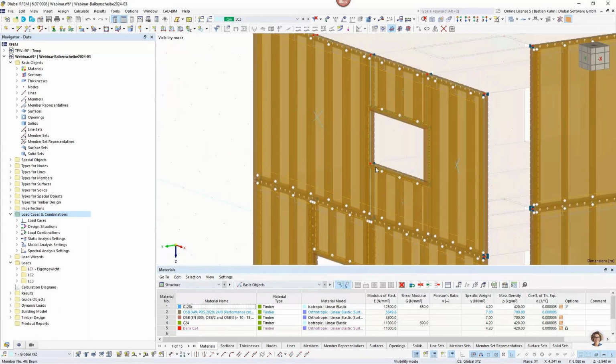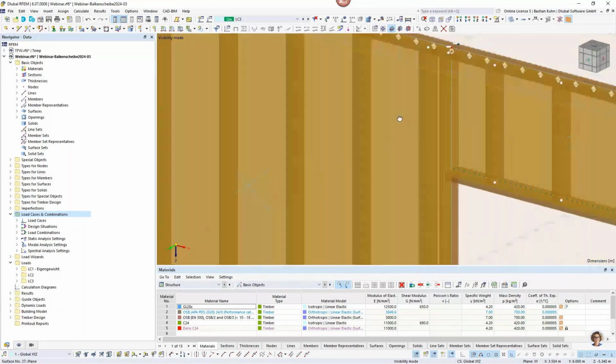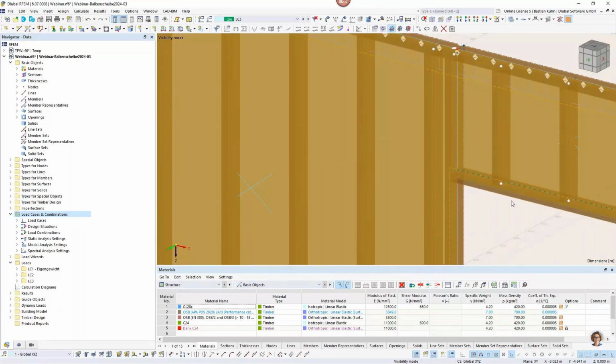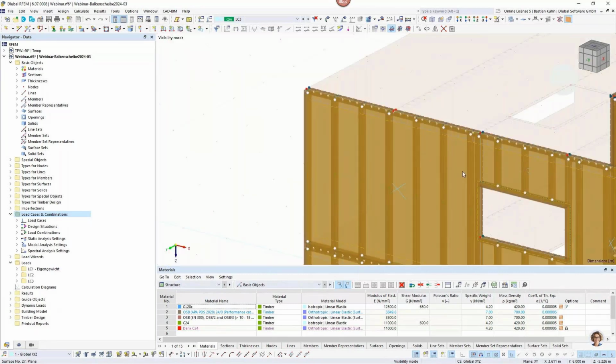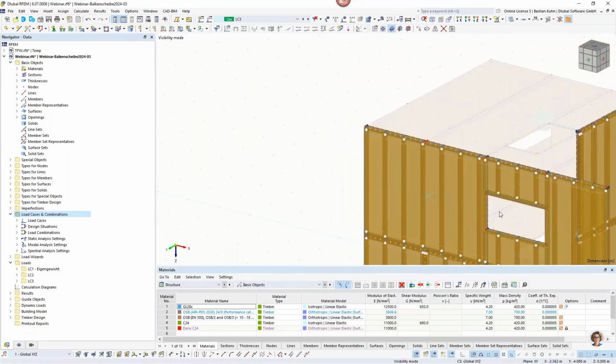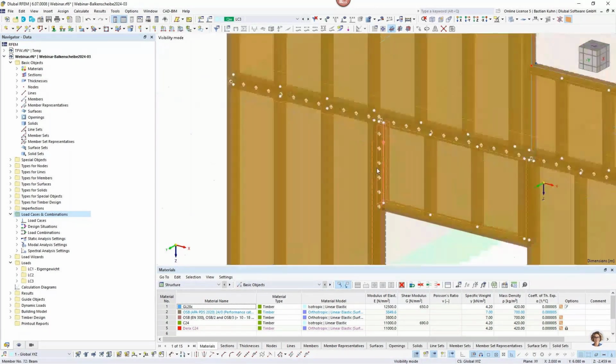Then what we do here in Europe is that we are using the top beam, or how you call it, on this window, and move it to the next stud. That's one of the possible constructions, and then it's a complete shear stiff, and of course it's nailed on every part wherever our OSB plates are connected or coming together, and there's always a beam or a post behind it. That's where it can be nailed on. That's for sure.